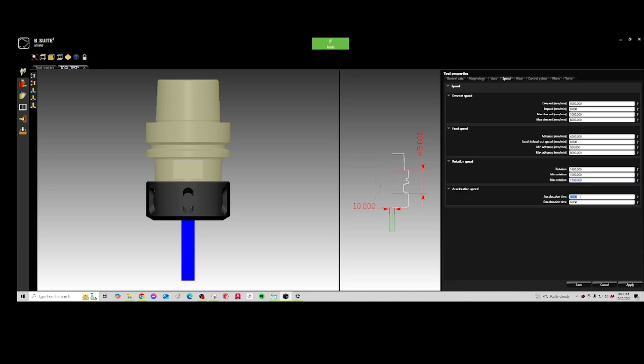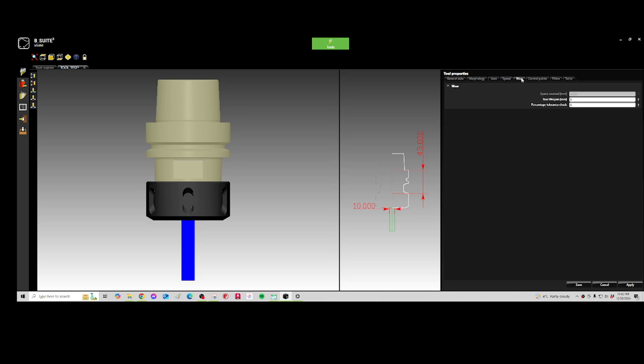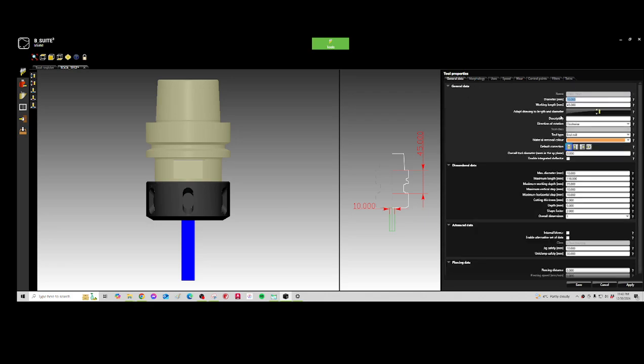Okay, here usually I use 3-4, so should be okay for both. This is acceleration time and deceleration time. This is how long it takes to go from one speed to another. Okay, you don't need to touch control points either, and that's pretty much that.